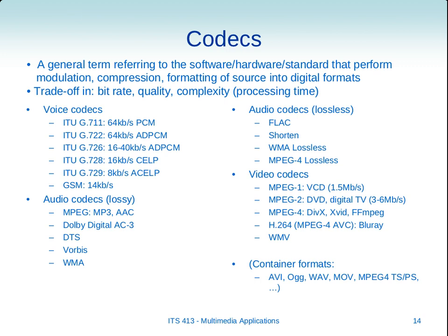Just some examples, different codecs for different applications. You've seen or used many of them. In voice codecs, there are different ones which require different data rates. PCM, some delta modulation, AD-PCM. Different codecs for different quality voice and use different amounts of capacity. GSM phones, at least in the older version, used a codec which required a capacity of 14 kilobits per second, less than the normal 64 kilobits per second, but at a lower quality.